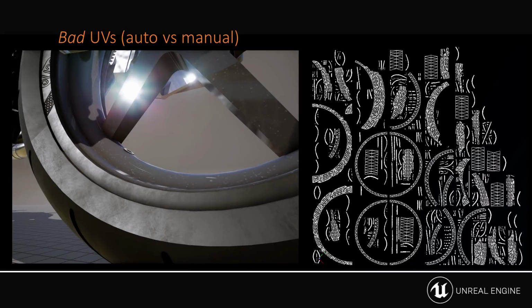And we can see up here on this corner that we don't have very good texture details. Something's going on in there. And there's also a seam, which is probably from the light map baking because of the bad UVs laid down in here. Now this tire is laid out using automatic UVs. As we can see on the right with these UVs laid out here, you can see the faces of them are scattered out quite randomly. And this isn't going to result in good texture placement.